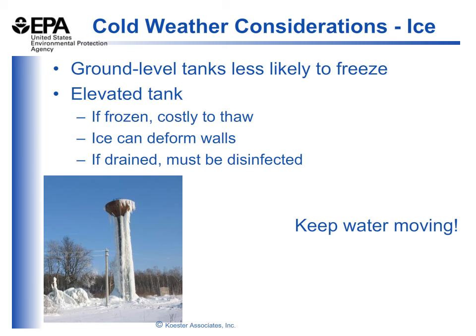Freezing of ground level reservoirs is typically not an issue because the water picks up some heat from the ground where the tank is located. It's normal for ice to form around the walls of the tank, and it usually will not damage the structure. But it is important to keep thick ice from forming on the surface of the water. This is usually done by keeping the surface of the water inside the tank moving up and down by varying system pressure. So each time the tank level is raised, warmer water is brought in. Another method is to utilize proprietary water mixing technologies, which can be purchased and installed to keep the water moving.